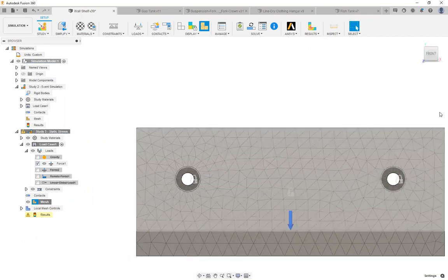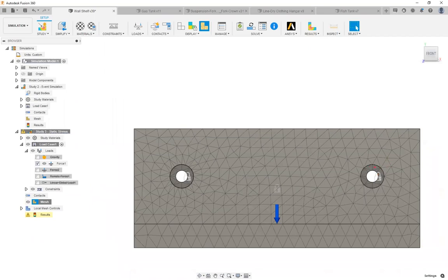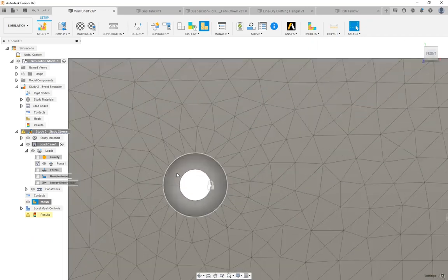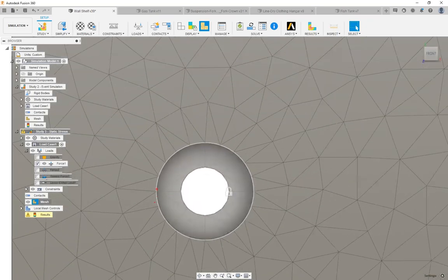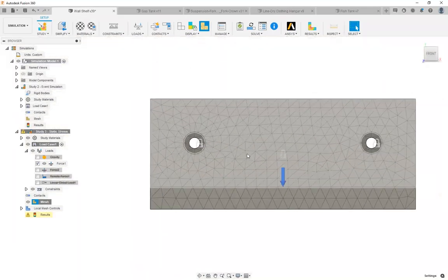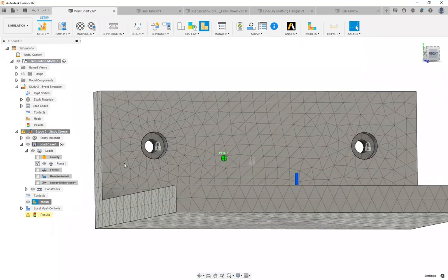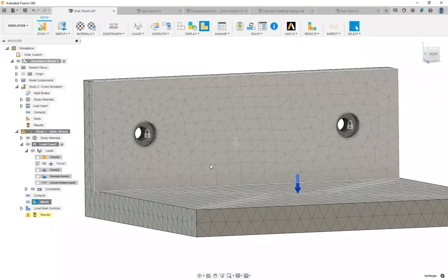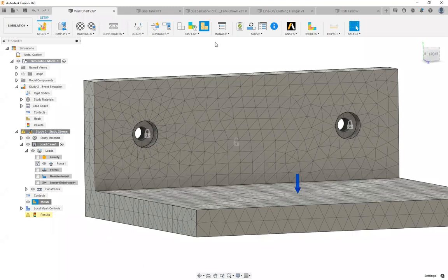We can even compare it to the one here on the right-hand side. As you can tell, this is not as detailed as the one over here. So let's go ahead and count this one real quick. 1, 2, 3, 4, 5, 6, 7, 8, 9, 10, 11, 12, 13, 14, 15, 16, 17, 18, 19, 20. That's right in between 16 and 24. So that's perfect. So that's something that you'd rather get a closer number to calculate for around cylindrical objects. I just use that as an example. But that's another recommendation we would give you for that.